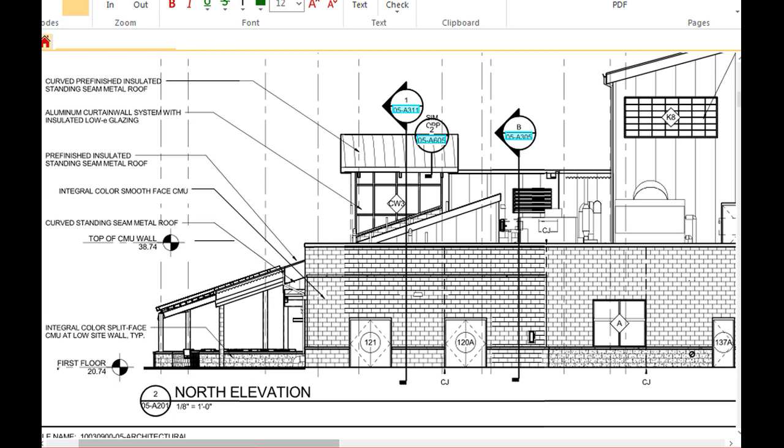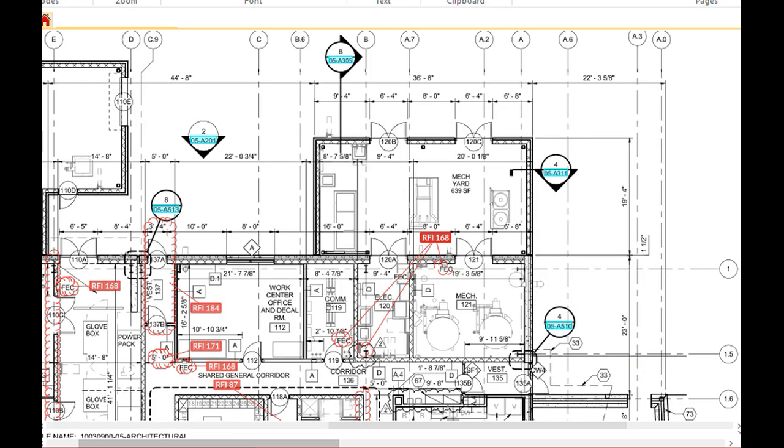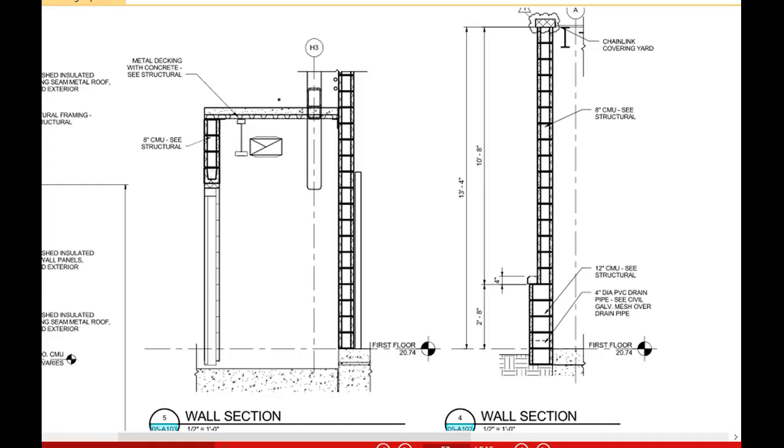Let's go back to the plan view and look at cut-through building detail 4, on sheet A311. Here, we have a wall side view with CMU wall details and dimensions, which is very important for subcontractors to make their shop drawings and for contractors when performing wall placement and inspection.